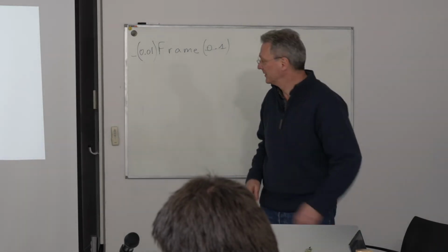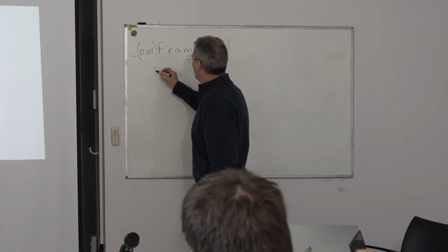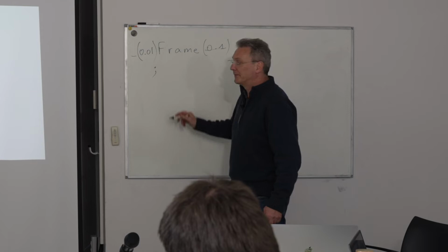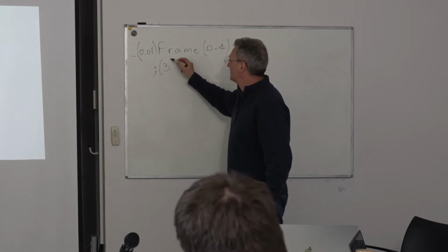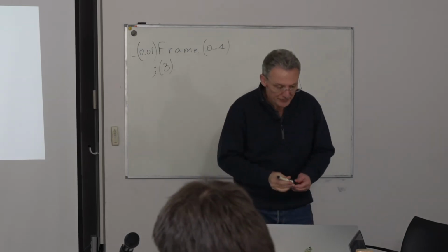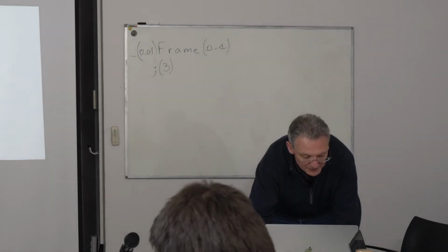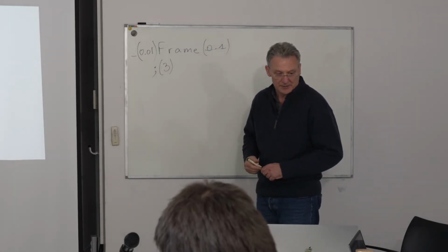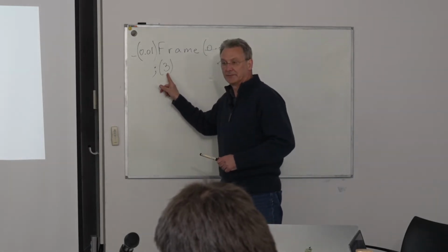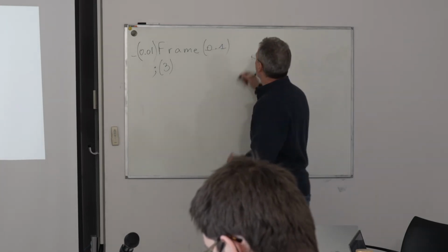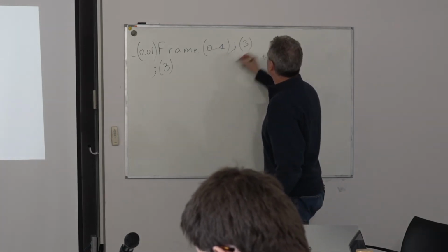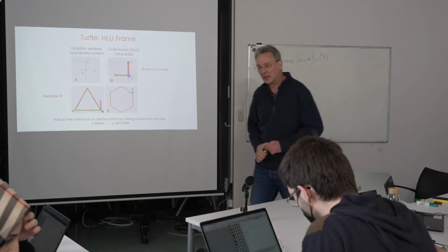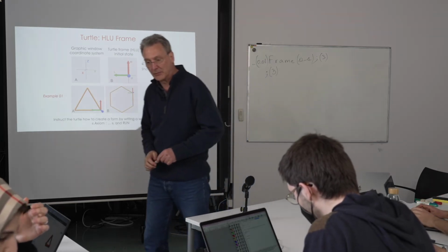And for the color, there is an instruction that is comma or colon. And then you can put a number here, and the number refers to the color map that is on the left. And if, for instance, you have the same color as me, 3 should be red. So if you put comma in the string here, with a 3, then you would see the color of your cylinders start to become red.